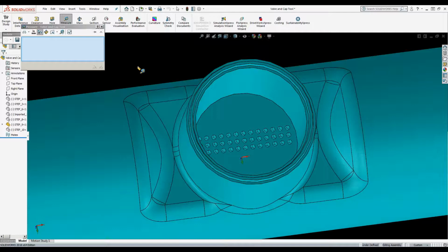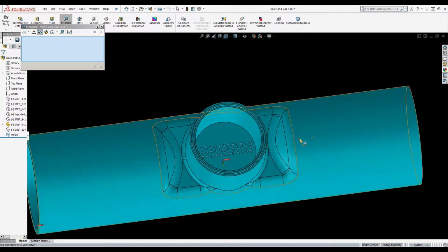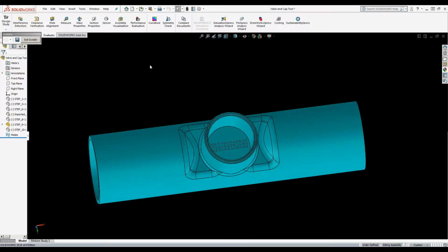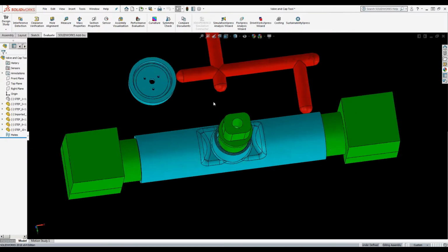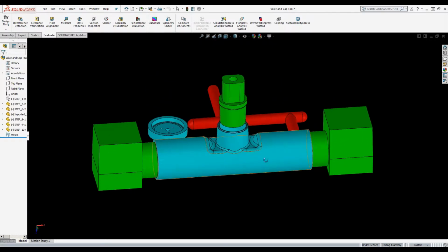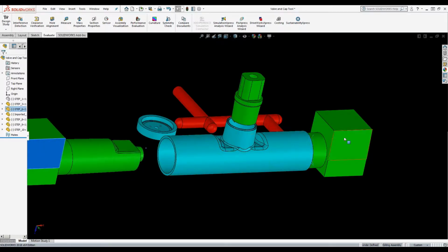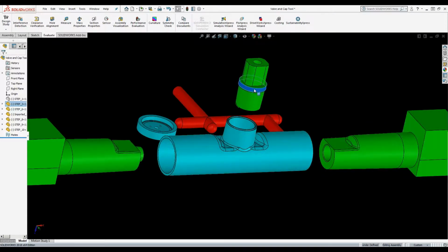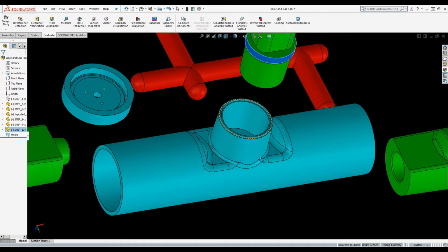Trouble with these holes being so small is cutting them in the tool, and actually let me bring up the tool so we can see how they're made and go from there. As you can see, this part has a few actions. These loose pieces here come out, and then this is the piece in question that shuts it off on this surface, creating those through holes in there.